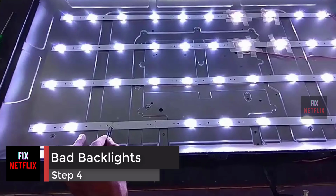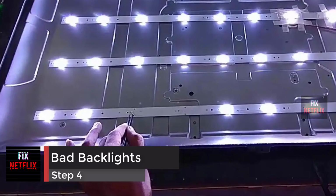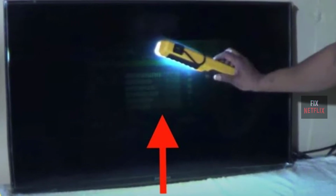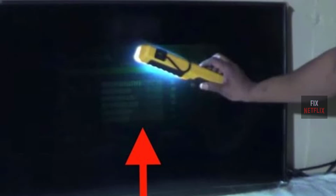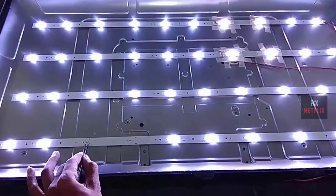Step 4. Bad backlights. This quick test will help you determine if the backlights on your TV have failed. Turn on the TV. Shine a bright flashlight at a slight angle to the screen. If you do see an image, this is a sign that the backlights have failed. The generation of the image means everything else is working properly.